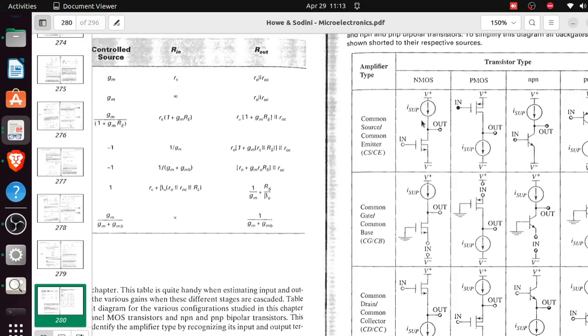That's not good, because if you want to get a current source externally to do that, it's not good, because this current source should be part of the circuit. Whenever a current source is here for a common source amplifier, it becomes part and parcel of it, and should also be sent for fabrication. So this ideal current source, you know it's ideal. You can't actually get a current source and just place it there.